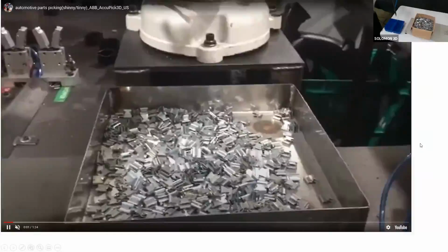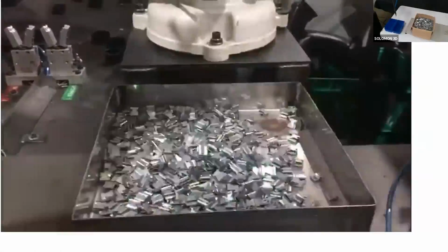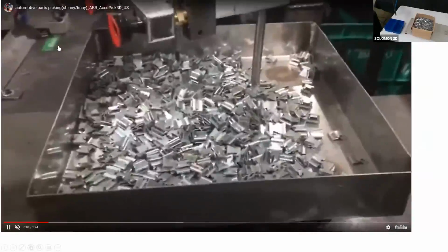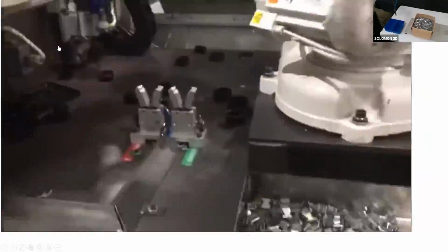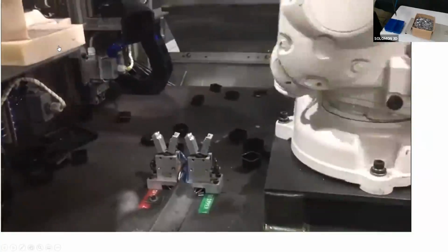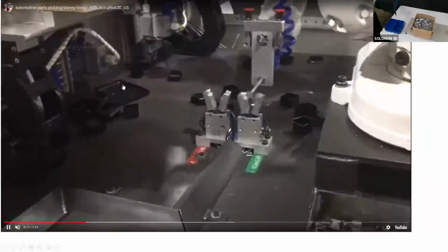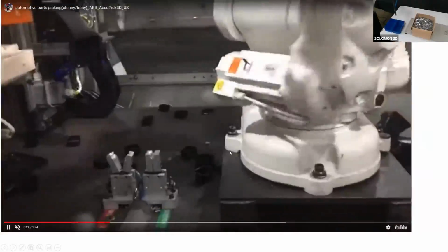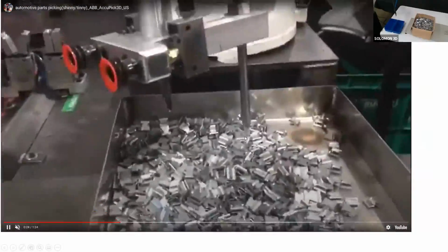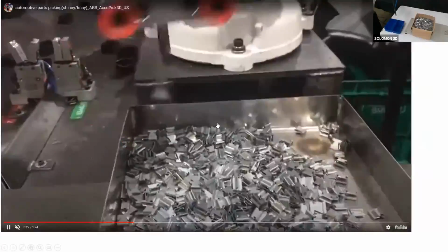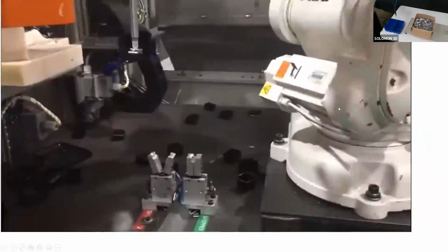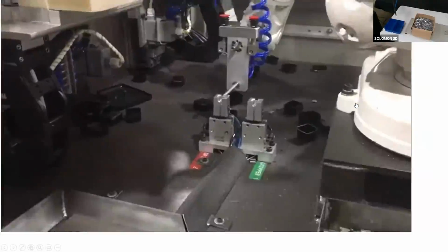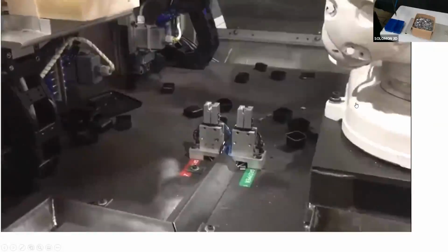So here's a more full bin of clips. We're going to pick two of them. You see these second stations here. We're going to be placing those clips onto the second station because they need to be picked up again in a different orientation to be able to be placed onto the plastic mold. So we place one. If you notice, every time we pick, we're taking a scan as the robot moves out of the way. That's a little bit hard to notice here, but that way, whenever the robot comes back, so there was a scan just there. Every time the robot comes back, there's already a pick point ready, so there's no downtime.